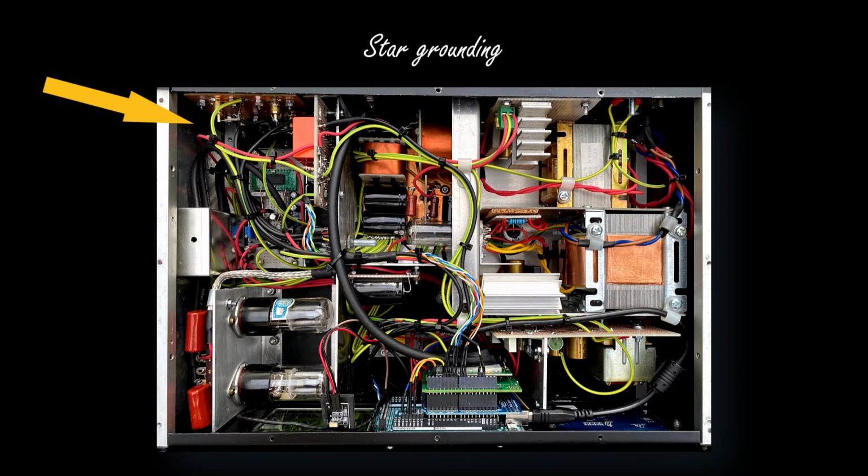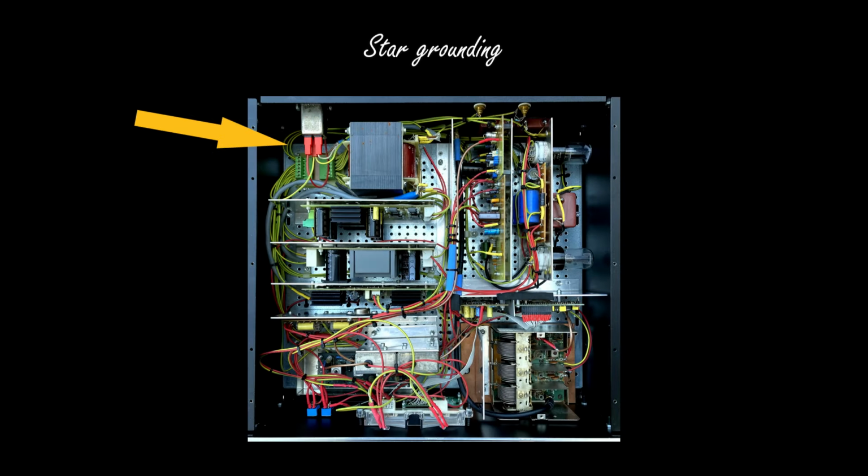Speaking of shielded cables, the shield of those cables should be connected to ground on one point only, on one side only. It's very important not to connect both sides of the shield to the grounding point, because otherwise we would create a ground loop. The safety earth within the power supply socket should be connected to the same star ground point through a separate cable.